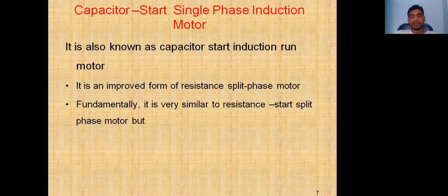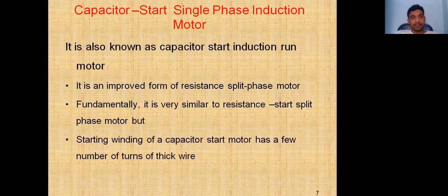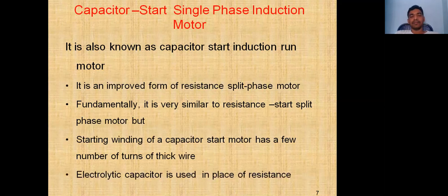Fundamentally, it is very similar to a resistance start split phase motor, but the starting winding of a capacitor start motor has a few number of thick wires. An electrolytic capacitor is used in place of resistance.